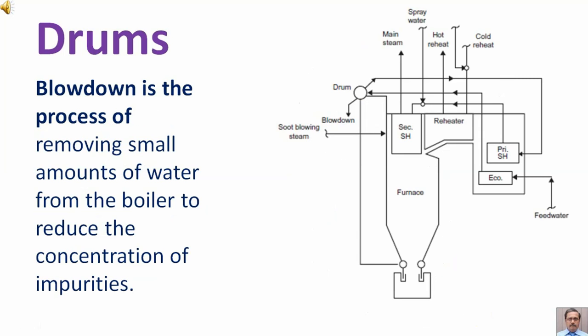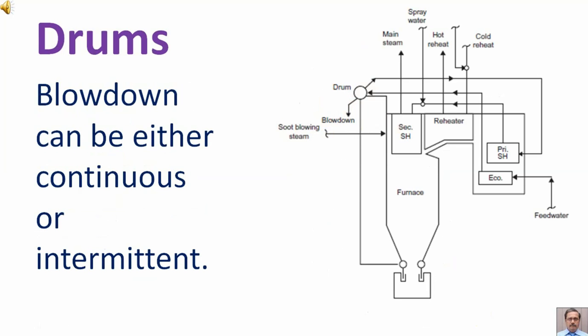Blowdown is the process of removing small amounts of water from the boiler to reduce the concentration of impurities. Blowdown can be either continuous or intermittent.